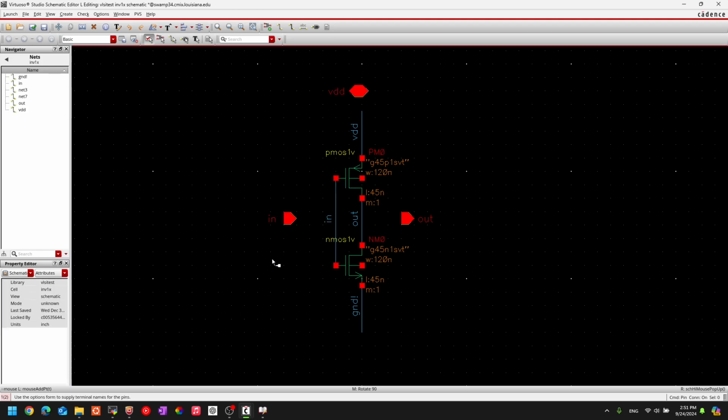Go back again. Now you could do it for ground, but you don't have to. When the label here is defined as ground exclamation mark, you don't have to place a pin for this. And I'd rather not place a pin here. Sometimes you could, but it's an extra pin to connect in the symbol or in the circuitry where you're using this symbol.